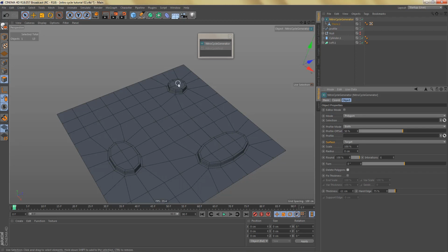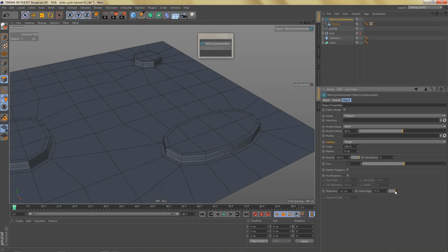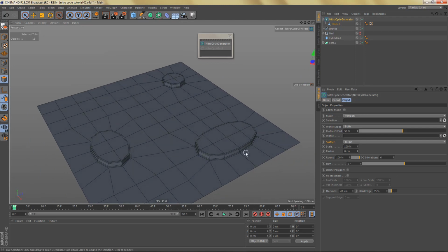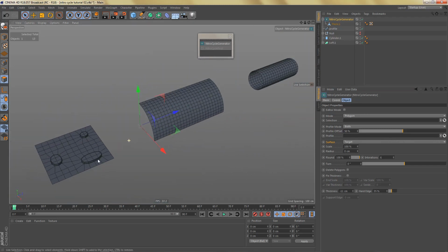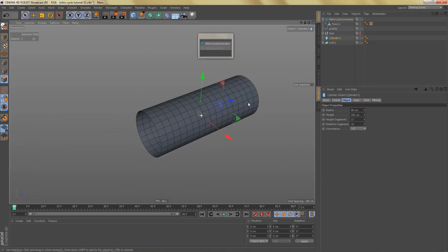these shapes upwards. Related to the thickness is the option to define the hard edges, which are the control edges that we need when we subdivide these shapes. We also have an option to fix the thickness. Now if I check this here, you won't see any changes. I'll try to show you this using a different object, and the object I will be using is this cylinder here.